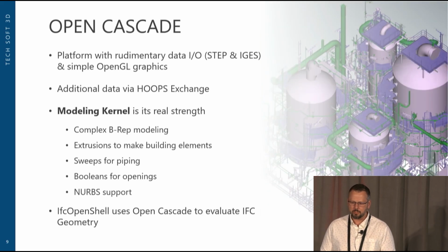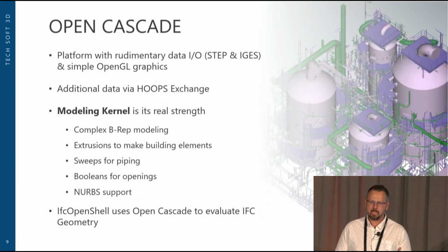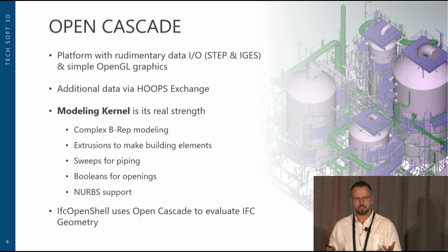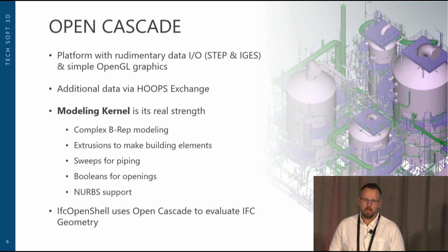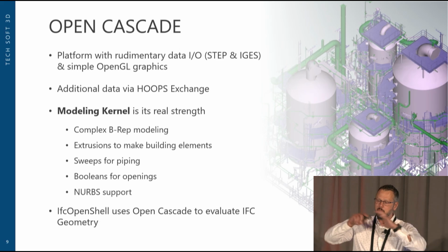Now remember, I told you about IFC data, where you have to do a little bit of modeling around it. Well, what's great about IFC data is it represents walls as objects, and it represents a door as an object within that wall that's actually a cutout. It's called a Boolean operation. So they actually don't tessellate out many times the wall with the borders around a door or a border around a window. Instead, they say, here's a solid object, and here's a cutout of that solid object.